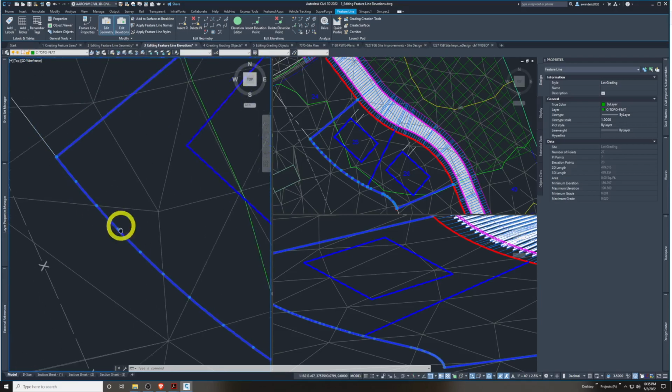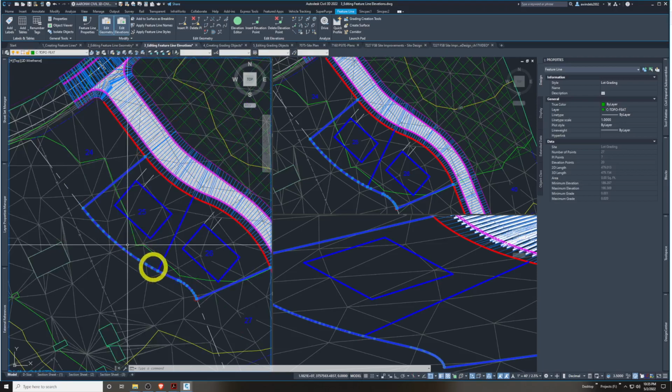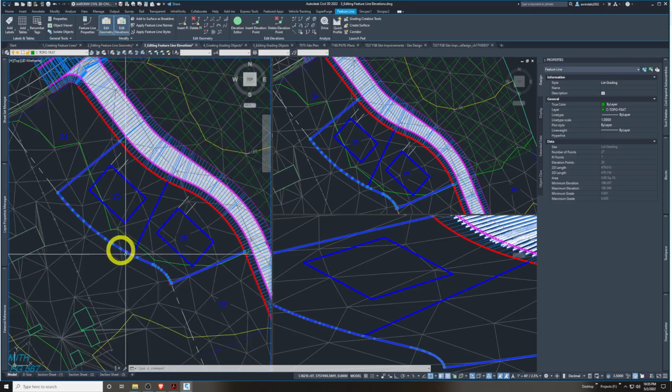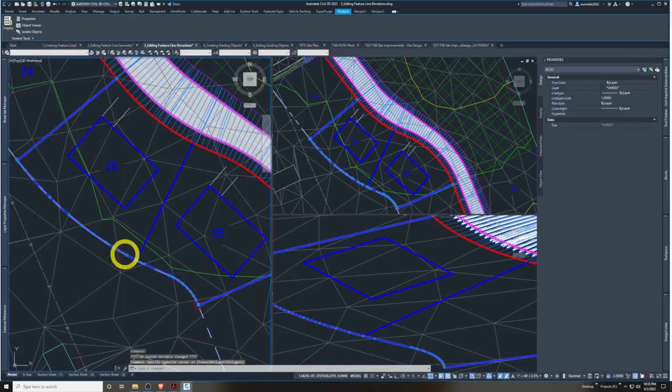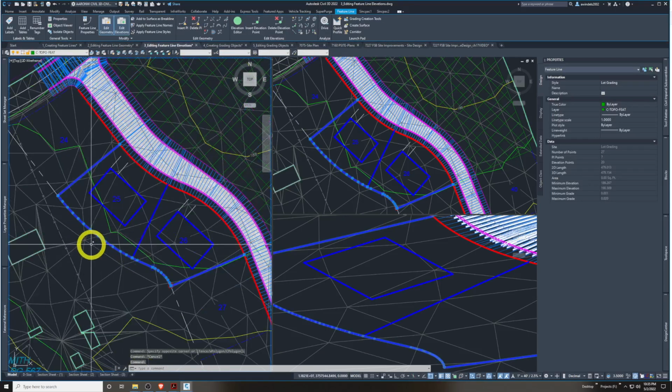It got those for sure, and it added some more even. But it definitely does those plus more, depending also on the variability of your surface, how much its gradient changes. So I just turned on the existing ground surface to show you that is what it sampled. So this feature line that we just made, with all these points of intersection and these elevation points, sampled this surface.